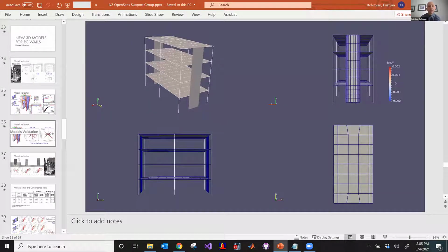So for all the building examples. Good, because I think the 2D SFI only works with the concrete CM. Right. That's another thing we need to add to OpenSees. On the side, we modified that fixed strut angle model so it works with other material models, especially Concrete O2, because that's the most stable one. So you would have to do that modification to make it work.